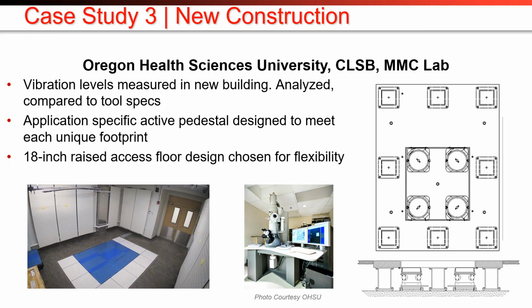So what they did, we would consider this the best case approach or the best practices approach. They decided to use an 18-inch tall raised access floor for flexibility, so they would have access to the underside of the instrument and access to the isolators if ever they needed that. And you can see the image on the right showing the inner isolated platform nested into the outer rigidly supported platform. Photograph on the left showing the platforms taped over with vinyl before the tool has been installed.